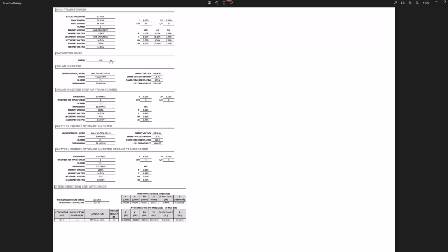You have a charging capacitance between your phase to ground. And by nature, together with your series impedance, such as a collector cable, transformer, etc., that's an LC network. So it's very easy to introduce, I would say, resonance points in your network.